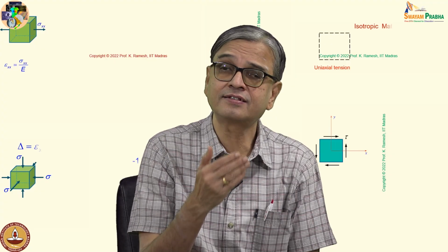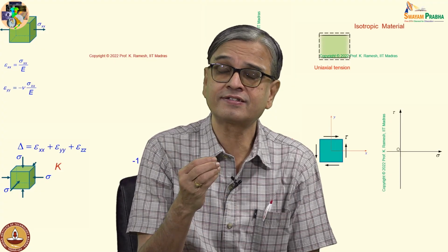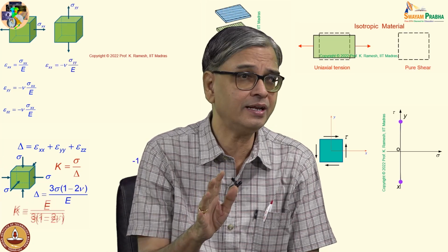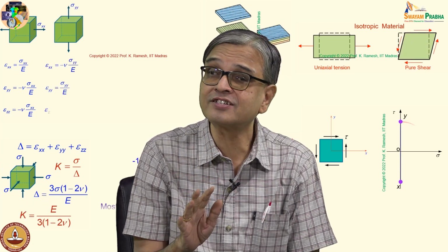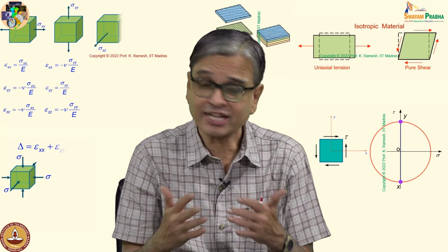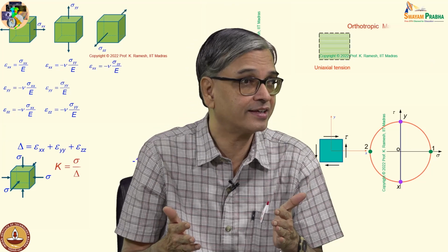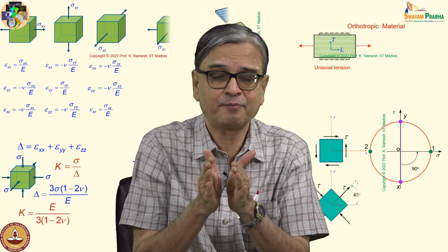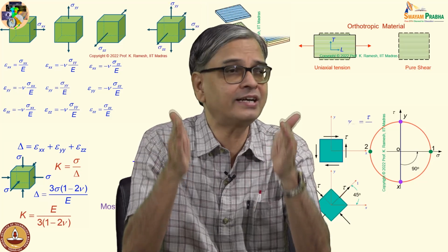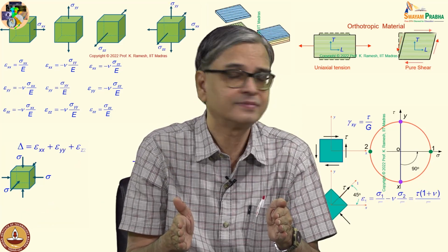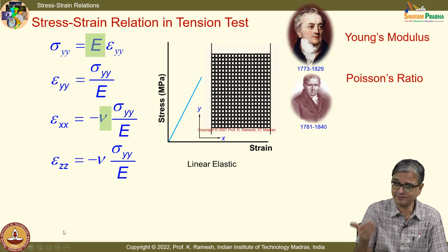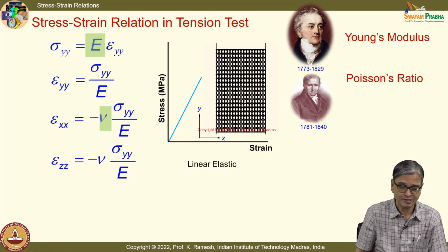See, while we discussed strain, I also said imposing uniaxial stress is very simple. Imposing uniaxial strain, I have to take extra effort to constrain, and for that what I did was I simply compressed, bulging out I prevented by a rigid block, and you had uniaxial strain. But biaxial stress will be developed, that is a different issue.